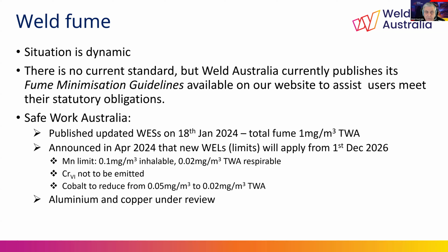Weld Australia has revised these guidelines on multiple occasions, taking cognizance of both IARC's ruling on weld fume and cancer in 2017, and more recently, Safe Work Australia's revision of their workplace exposure standards for airborne contaminants released on the 18th of January 2024 that reduced the exposure standard for total fume from 5 milligram per cubic metre to 1 milligram per cubic metre on a time-weighted average over an 8-hour period.